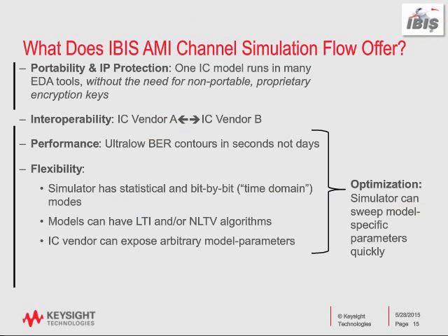Now, we talked about needing to use IBIS-AMI modeling. And again, this is where our VCSEL will fit in a moment. IBIS-AMI is a particular kind of model that's meant to run with a channel simulator. It basically is a portable model, and it's got inherent IP protection because the model is actually compiled. So that's a good thing. And the other thing is that this model is also transportable to other simulators that meet the IBIS-AMI standard. So you don't need proprietary encryption keys for modeling to protect your IP, and that's a really good thing.